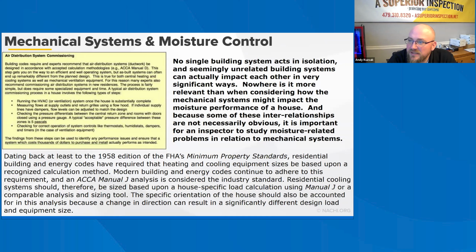First, indoor relative humidity levels are increased as the AC system reduces the air temperature but removes moisture to a much lesser extent. Second, due to increased indoor humidity and discomfort, occupants may lower the thermostat set point temperature to compensate. As a result of cooler indoor temperatures, approximately less than 75 degrees, and higher indoor relative humidity levels, condensation is more likely to occur on windows and doors, on the inside of wall cavities, on concrete floor surfaces, and on floor sheathing and joists above crawl spaces.